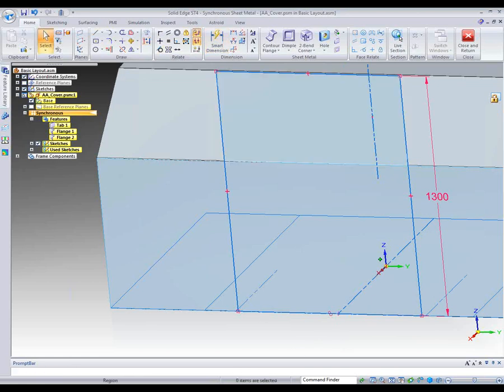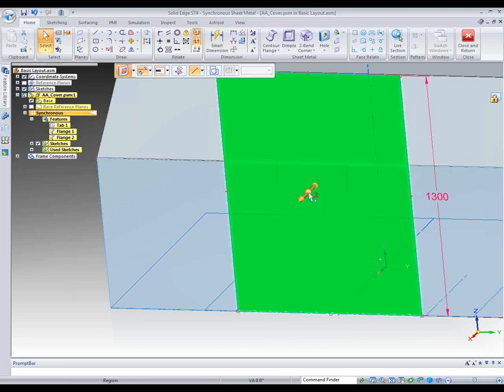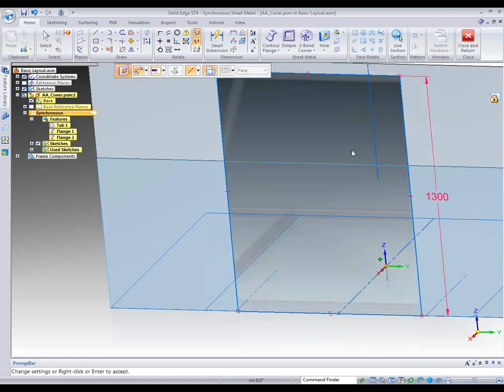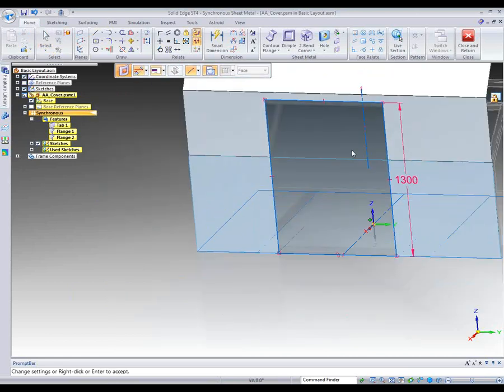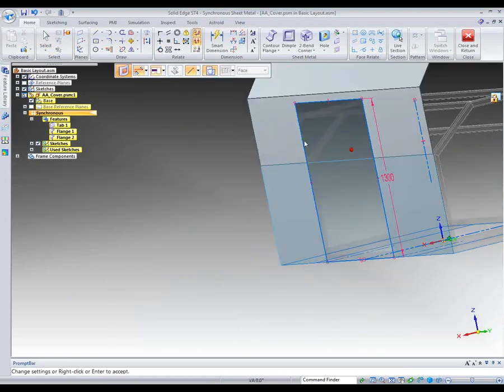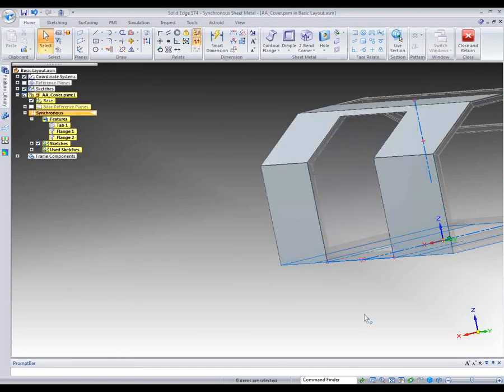And I'm going to use my select tool to select. My grab and go handle's ready there to push that through. But what I want to do is to do a wrapped cut. So what it does is when I push that through, you'll see it unfolds the bend that went across to cut it through on the normal. And then it places it back, and you can see that edge will be normal to the face. If I just pushed a cut straight through there, that edge would be beveled. Okay.